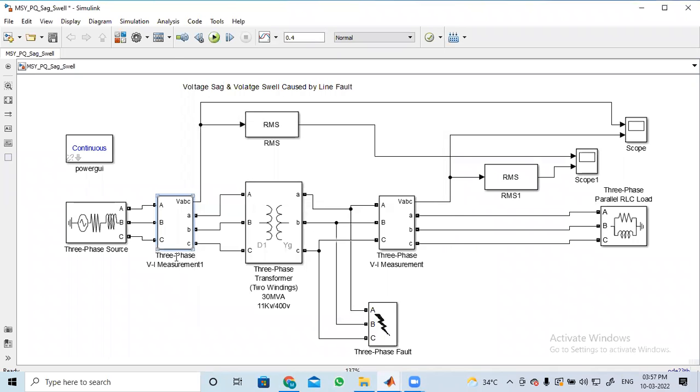Okay, and here we can give the name also, this one. Select all, that completely selects it. 11 kV bus, we can enter this one. This is 0.4 kV bus, we can enter like this. It is not entered 0.4. 0.4 kV bus we have used.